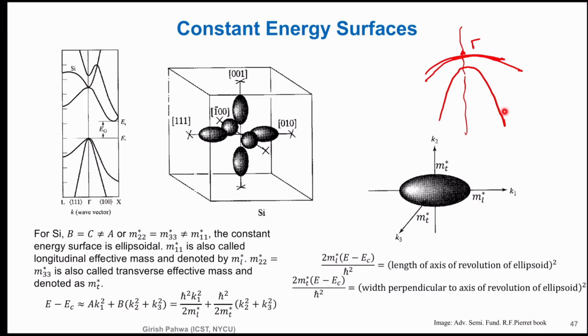So you have three different effective masses for the holes, because there are three different curvatures at the gamma point. These two are overlapping at the gamma point. It means the maximum energy point for these two bands is at the same point. And this is a little away, so this is called the split off band, split off branch.